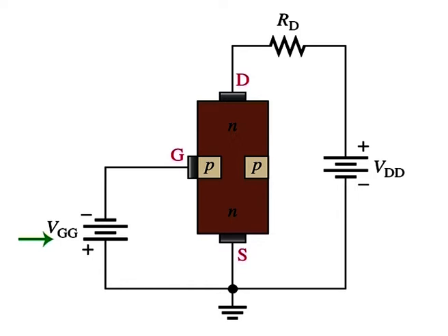The JFET is always operated with the gate source p-n junction reverse biased. Reverse biasing of the gate source junction with a negative gate voltage produces a depletion region along the p-n junction which extends into the N channel and thus increases its resistance by restricting the channel width.